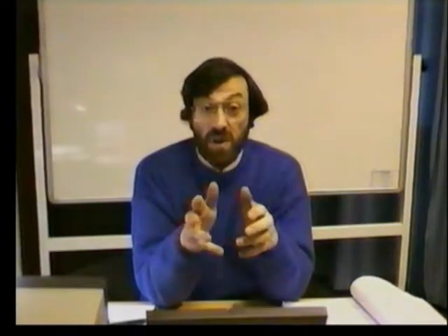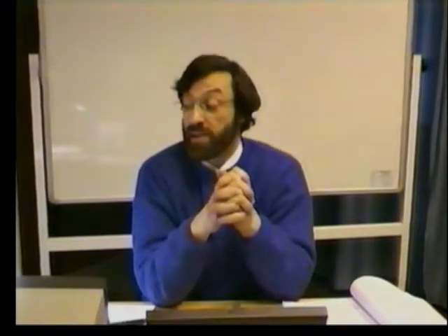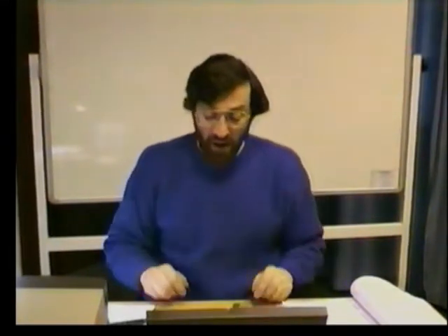If an integral term can go crazy, it will. They're like that. They're not very predictable. They're very good at getting rid of steady state error, but if they're too large, they will make your system go unstable and critical. So take great care with them. How can we control the I term? Well, there are some traditional control techniques, but with the advent of modern computing, I want to show you a few computing techniques which are much, much easier for us to implement.